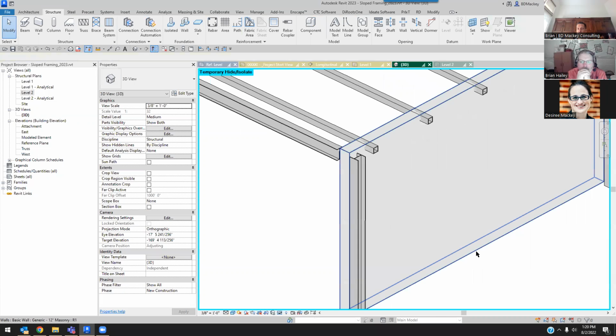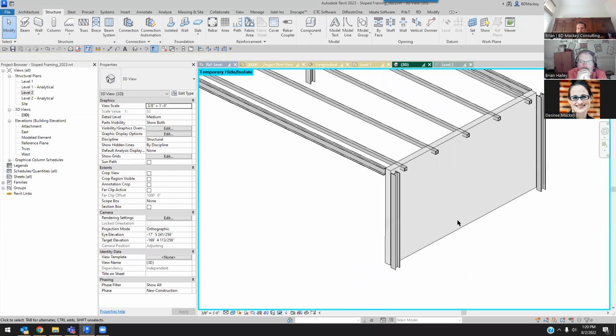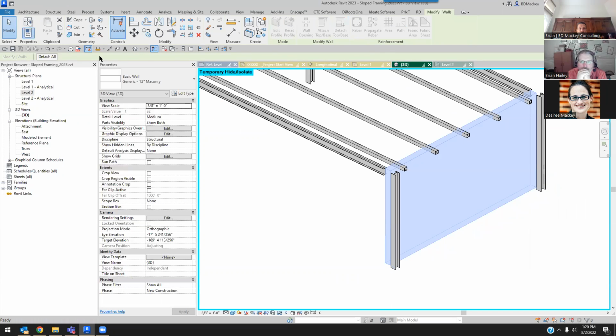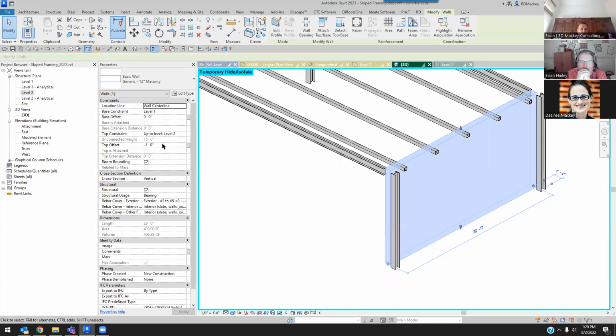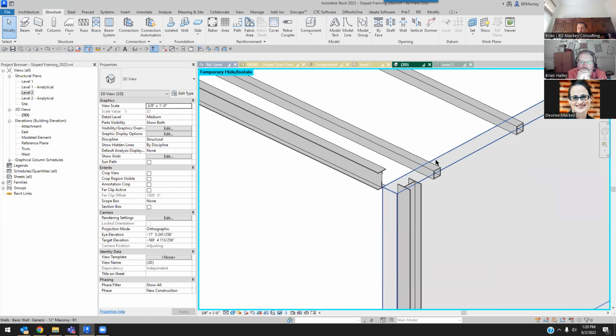So if this was one of those cases where this wall was going to be sitting down a foot or whatever, and I wanted to go through and see that, then yeah, I model my little reference beam. I have a subcategory. This must be attached. Let me detach all. Detach all. Now come in here and say my top offset is 1 feet. I don't know why it's not going down. -2 feet. There we go. Now I can graphically show these where I want, and also model them in the right location.